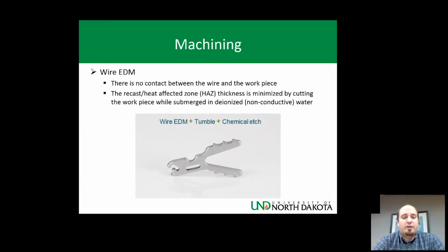SMAs can also be wire EDM'd. A spark discharges from the wire and ablates the material closest to the wire. There is no contact between the wire and the workpiece during the cutting. The recast heat affected zone thickness is minimized by cutting the workpiece while submerged in deionized water.